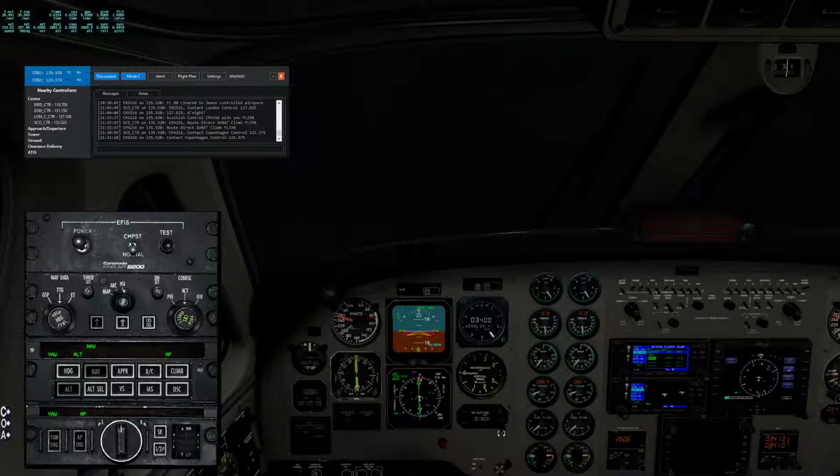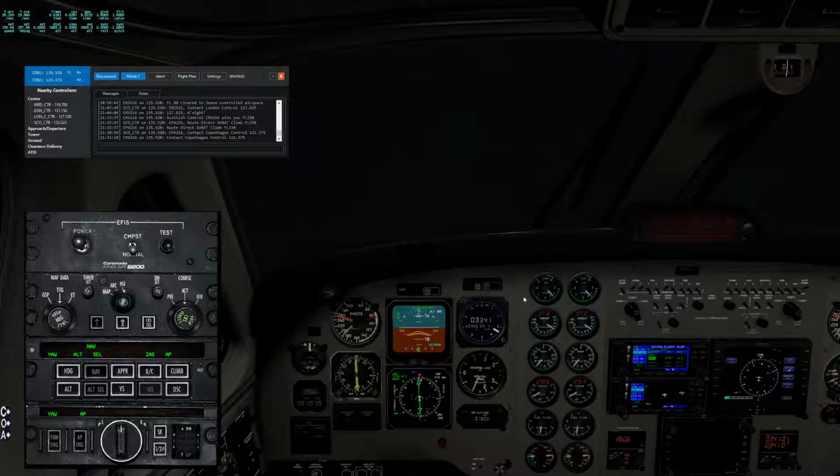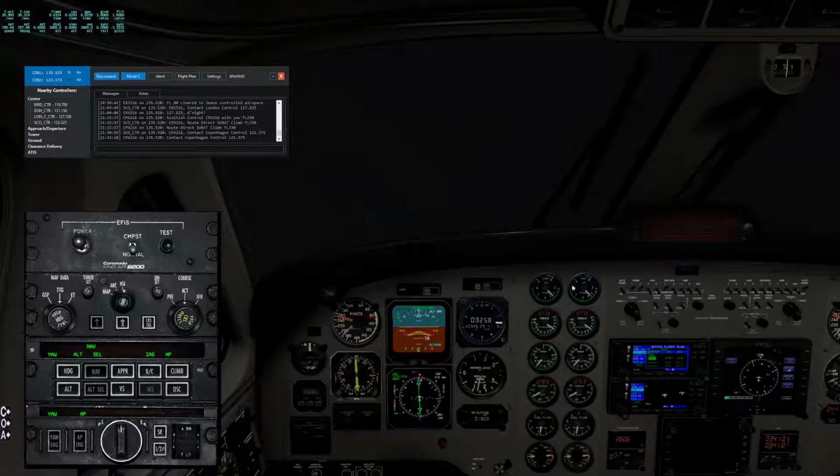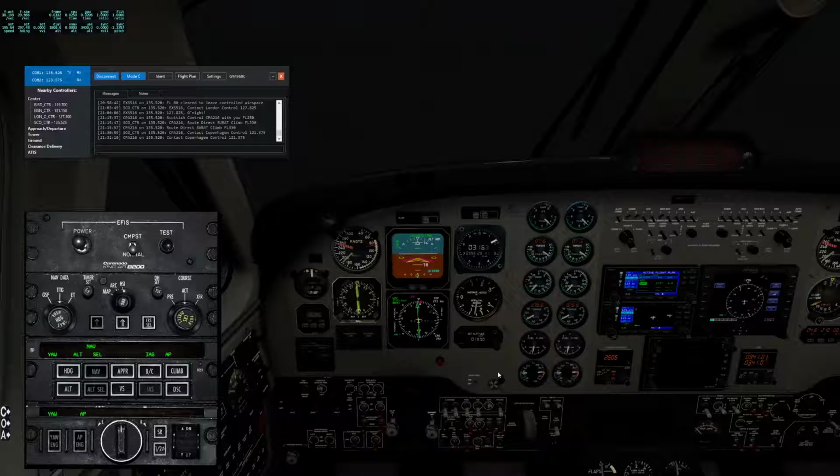So I'm now taking us down to 1800. Rather more sharply than you would normally want at this late stage, but it's okay. We've got enough distance because we need to fly out now to 8 DME. We're at 4, so we'll just about make it. You can see some clouds now in front of us. Hopefully, this is another problem I've got, is that of course it's been cloudy most of the way, and I'm